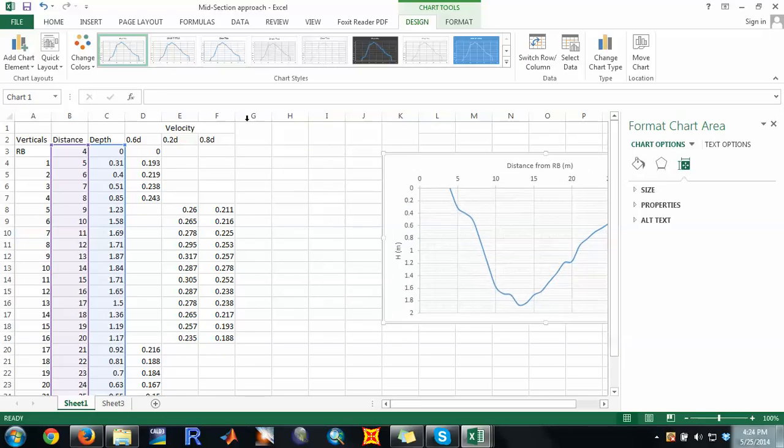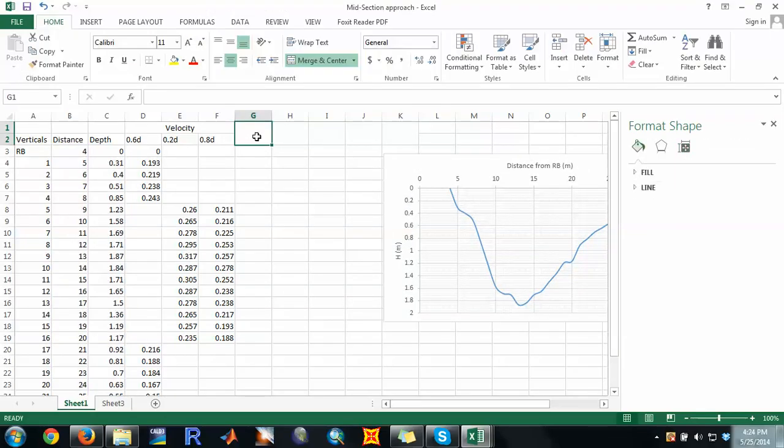So the first thing is you can find the area. To find the area, we have to calculate the b first. For the corner parts, we can approximate the area with a triangular section, and for the mid sections we calculate the areas by using the trapezoidal approach. So first let's find b.